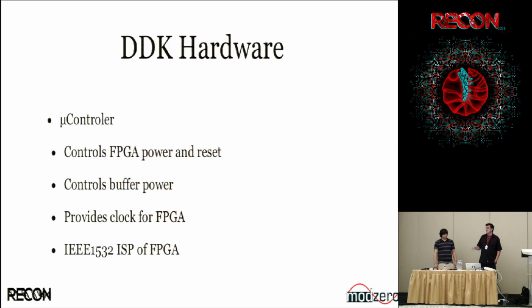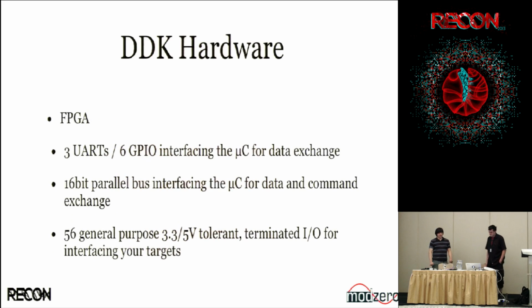Also, we implemented code to flash the bit stream for the FPGA. Fortunately, the microcontroller, as opposed to some cheaper ones, is big enough to store a full FPGA bit stream in the hex file that we distribute on these. So if you ever mess up your board, if you use, for example, an external programmer, and you want to go back to start, you can do it. It's not a problem. You can just erase it and flash it again using the command line interface, which we'll see in a little bit.